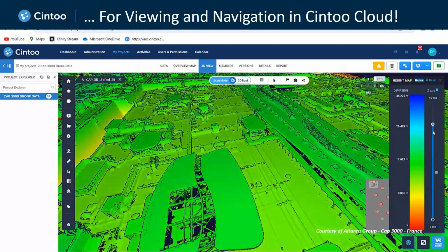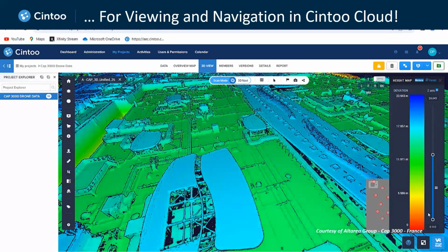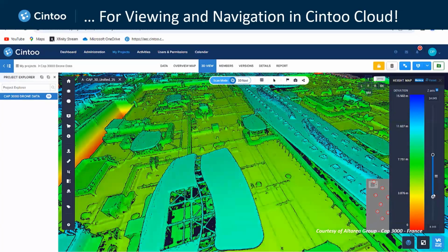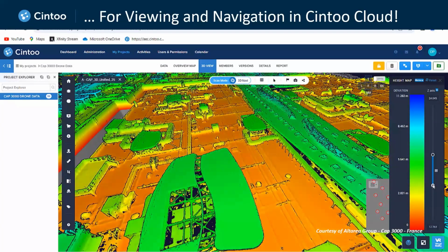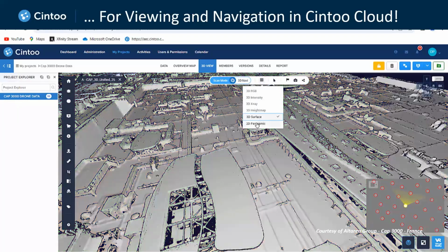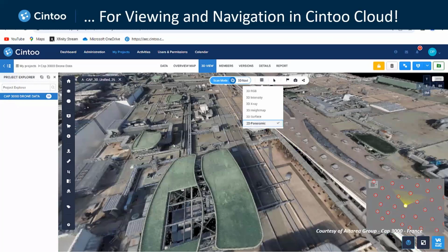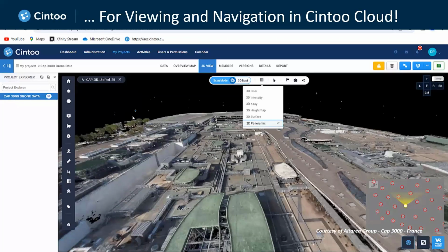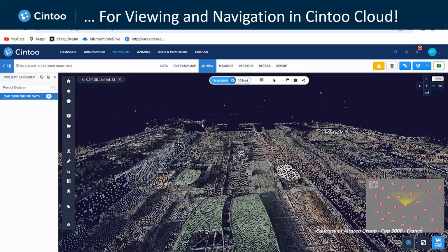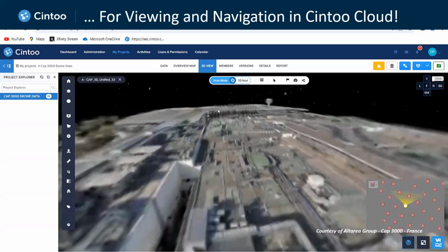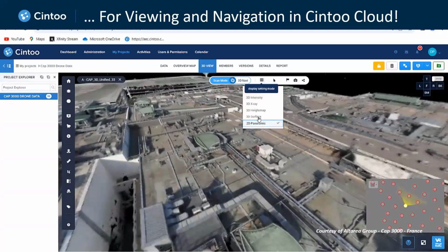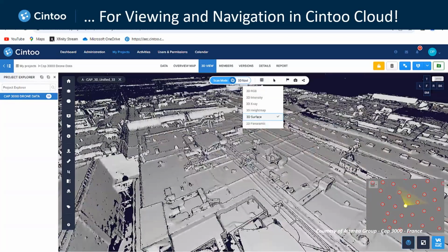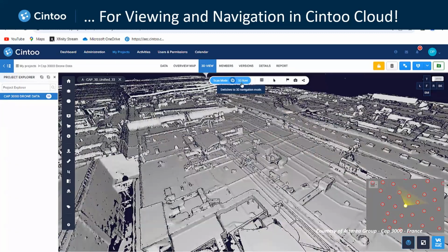Then you can use various shaders we have with the 3D mesh. You see the quality of the mesh we have produced from this point cloud. For example, this is a height map. Going back to the 2D panoramic image here, going to the next vantage points. Those vantage points, we call them virtual vantage points. It looks very similar to what you get from a static scanner.